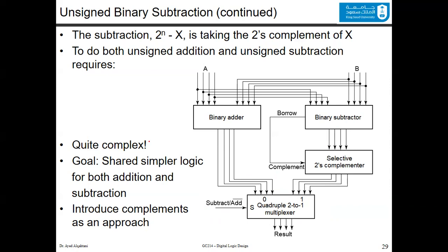Now, this is actually quite complex. And actually, we did the subtraction in a tedious way. So our goal is to try to design a shared, simpler logic for both addition and subtraction. To do this, we will revisit the complements, and after that, we will notice a simple manipulation to convert the subtraction into addition, and we will find that the end block diagram is super easy compared to this big block diagram.